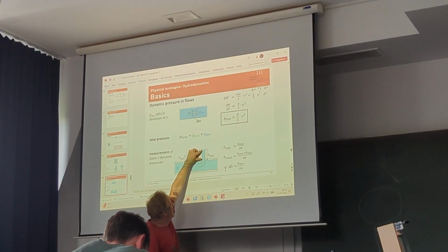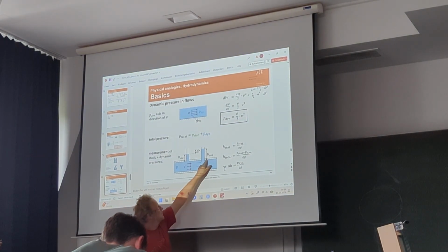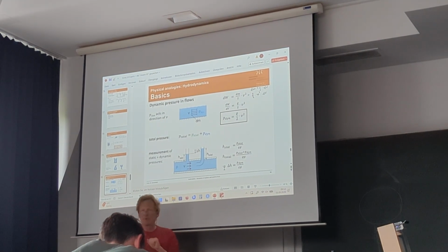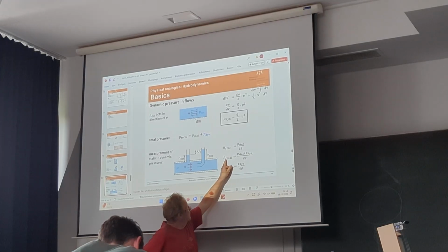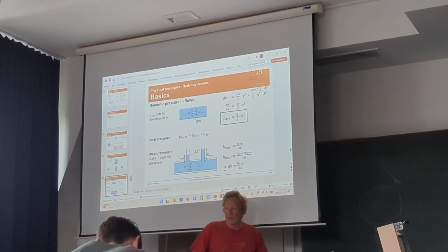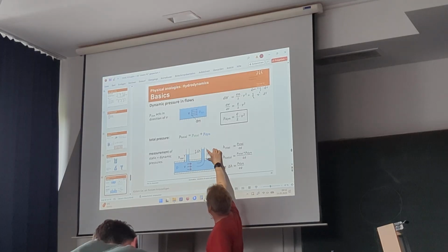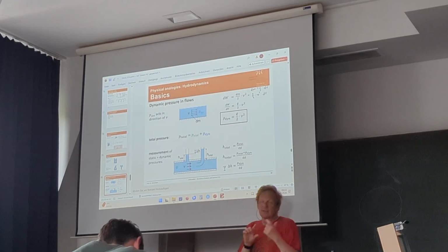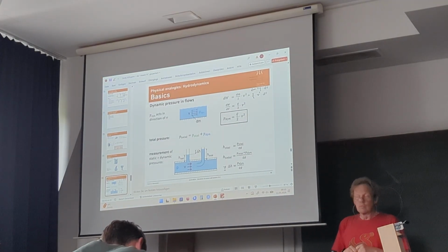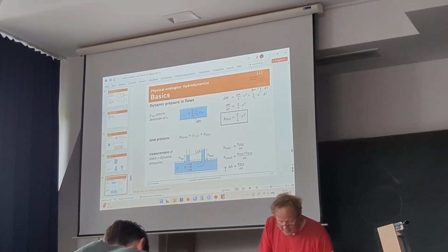The pressure which rises here up to a certain height as water means that in this total height we have included both the static and the dynamic pressure. So we get this total height due to the sum of both. That's the total pressure divided by rho and g. And if you measure both the total pressure and only the static pressure, then the difference of course yields also the dynamic pressure itself. So all 3 kinds of pressures can be measured. That's the important thing here.